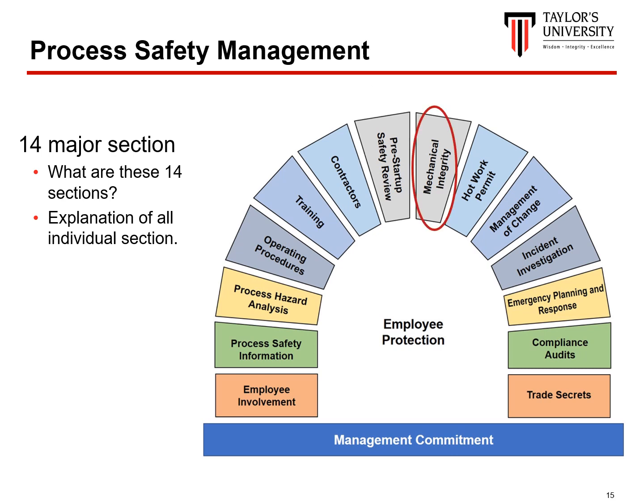The mechanical integrity section of the PSM standard ensures that the equipment, piping, relief systems, controls, and alarms are mechanically sound and operational. The requirements include, first, written procedures to maintain a functioning system, training regarding preventive maintenance, periodic inspections and testing based on vendor recommendation, a process to correct deficiencies, and a process to ensure that all equipment and spare parts are suitable.